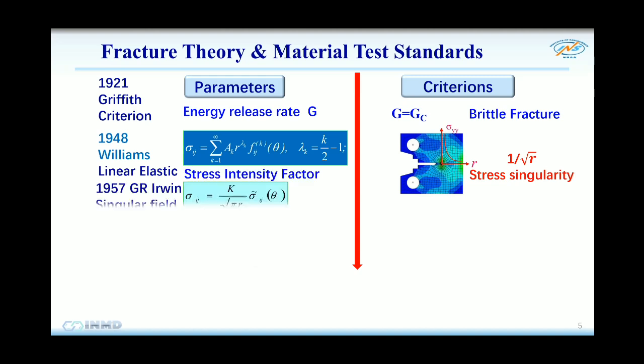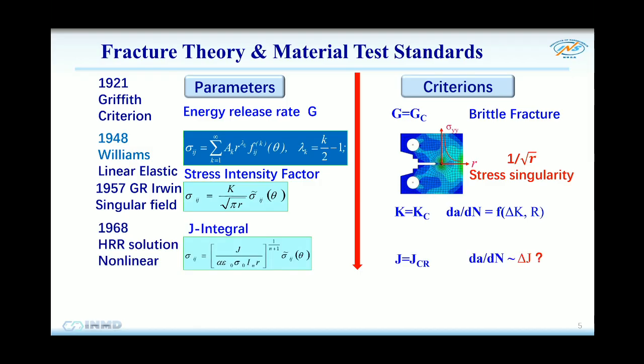Irwin proposed the stress intensity factor concept, which makes it easy to apply fracture mechanics to engineering problems. In engineering structures, toughness and plasticity always occur at the crack tip.